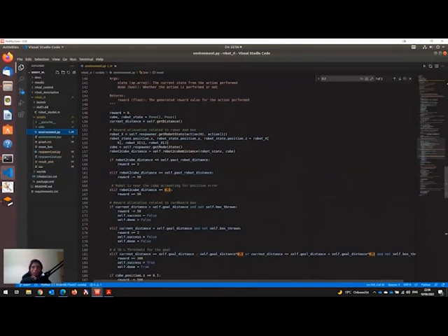It will reward using different stages of the goal. Here the goal position is the position of the cube that is 0.5 meters distant from the initial cube position. The box thrown down the table will be rewarded negative, and once the goal is reached, a positive reward will be given. An optional reward based on the Euclidean distance between the initial and the final position of the cube can also be implemented.